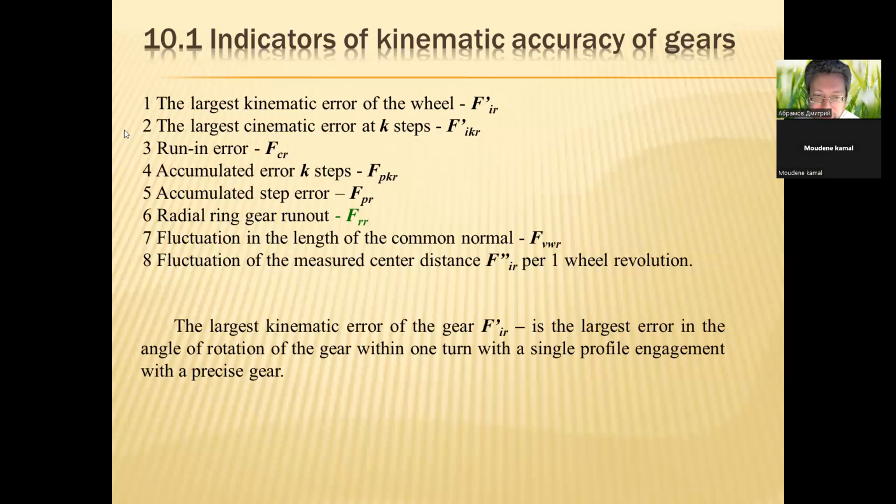The largest kinematic error of the gear is the largest error in the angle of rotation of the gear within one turn with a single profile engagement with a precise gear. Please write down to your notes these 8 parameters, indicators of kinematic accuracy of gears.